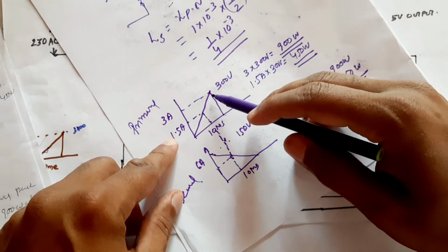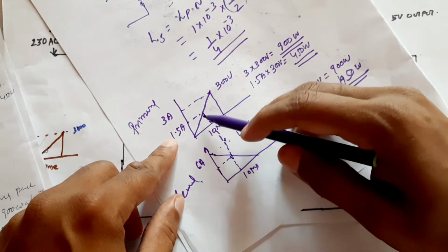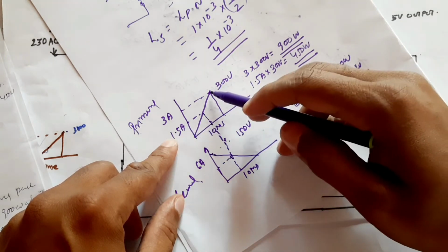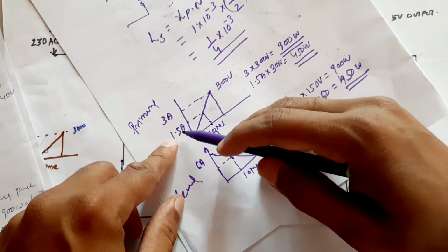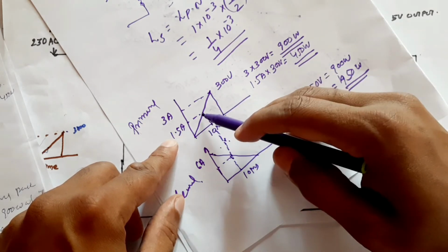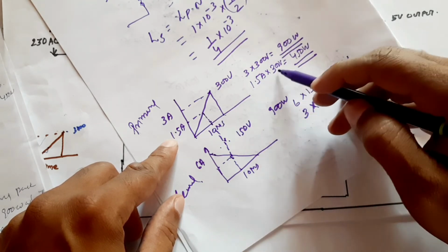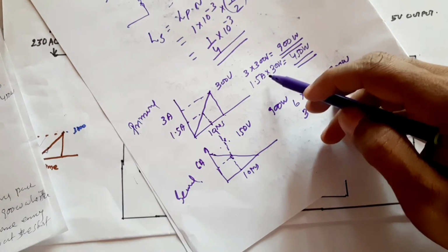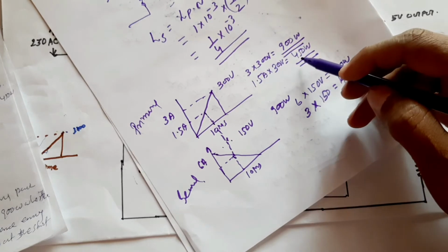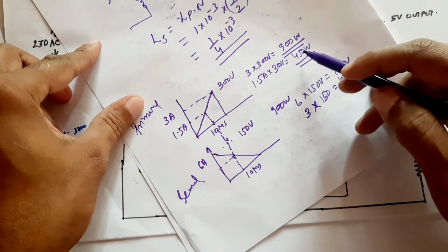That means 3 ampere of current at 300 volts gives 900 watt of power. And if we take half that time, say 5 microseconds, the current will not have reached there. The current will be around 1.5 ampere, and at that position, 1.5 ampere at 300 volts means 450 watt of energy is stored in the core of the transformer.